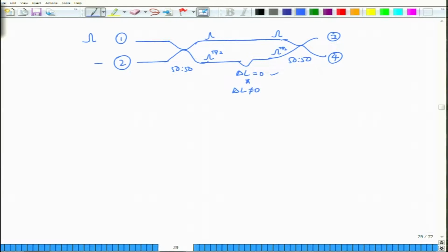Okay. So, now you have EI1, as far as the second coupler is considered, you have an EI1 and an EI2, and then you have to look at this output. Now, the idea here is that this light would come out with the same phase as the input here. However, the light that would be coming at here will be shifted by pi by 2. Now, pi by 2 shifting, and if you look at the directions appropriately, you can actually arrange that this direction will be pi shifted, but there is also another global phase, right.